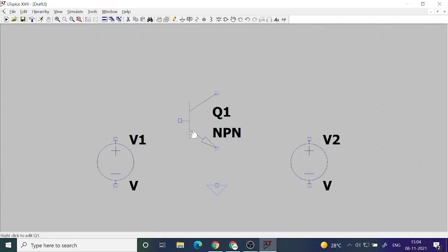Now this is an NPN transistor. That means base is P, emitter is N, collector is N. So you can think about a P material sandwiched between two N materials. And what we are going to do is bias these junctions. Just like we have biased diodes, either forward bias or reverse bias, I can also forward bias or reverse bias these junctions.